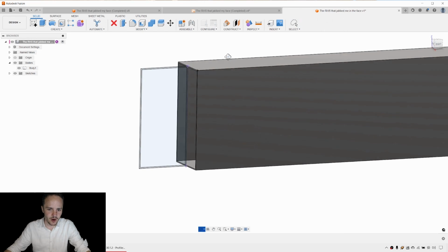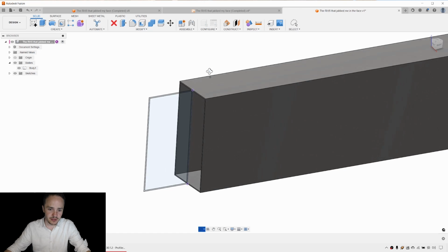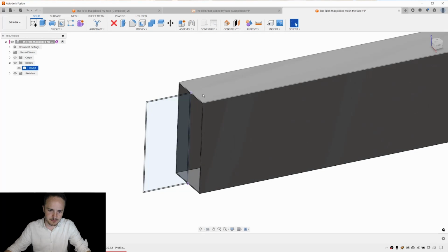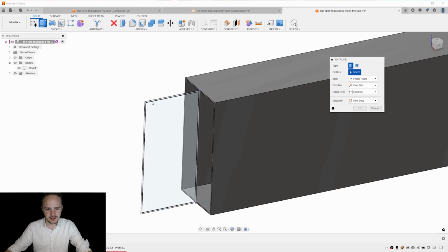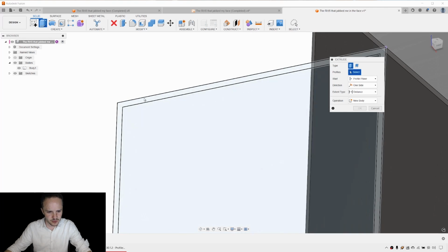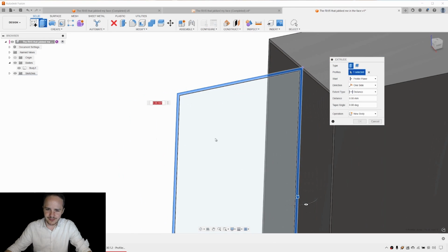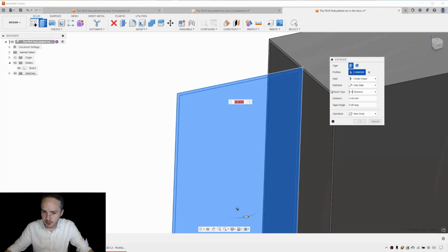Excellent. Okay, let's rotate our view, and here we can see the sketch is on the mid plane there, and it happens to touch our previous rectangular hollow section. So next, we'll come along and we're going to extrude as we did before. So hit E or the extrude button. Carefully select the profile we just drew. Click. If you accidentally select too many, like both of the profiles, you can unselect one by holding Shift and selecting it again.